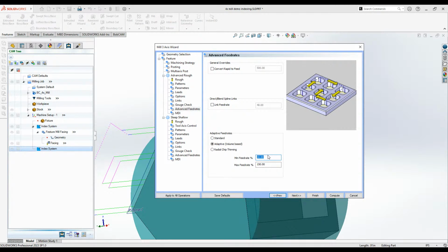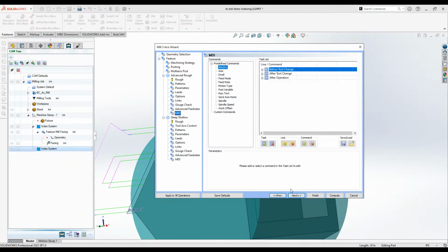What this will do is kind of like a look-ahead option in some of the machines. When the tool is getting into larger material at a time, like into these corners, the software can calculate how slow the tool needs to move to keep a constant chip load. And that can reduce chattering at the machine. So based on the volume that the milling tool is cutting out, it's going to calculate and set a smaller step over and keep a constant chip load. It's basically the setting there.